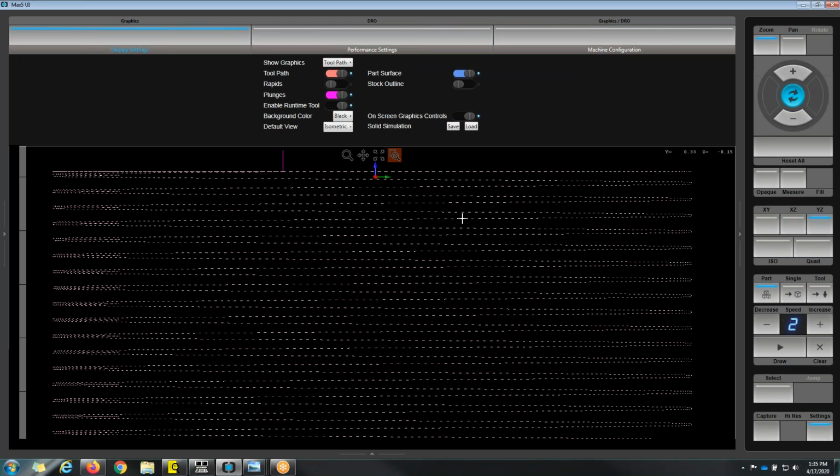So this is why we're going to get that nice smooth motion with the good surface finish. We're not going to have any transition where the machine is just plunging in Z. It's going to be a nice, smooth, consistent motion. And like I said at the beginning of this presentation, it's mostly preference, but I really do like that style of cut. That's why I use the helix option so much, and that's why I was so excited when we found that we could use the swept surface to get this style of cut. So I was no longer tied to the cam system in order to get this type of tool path.